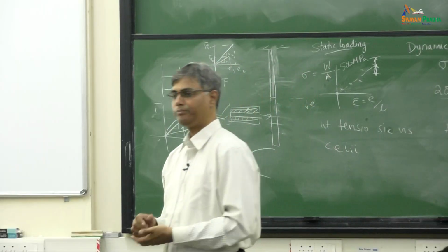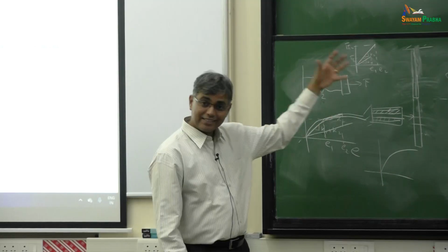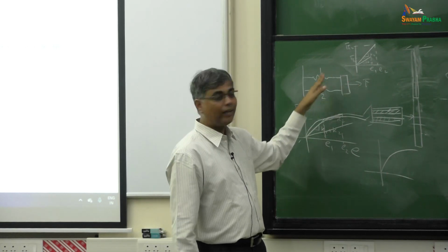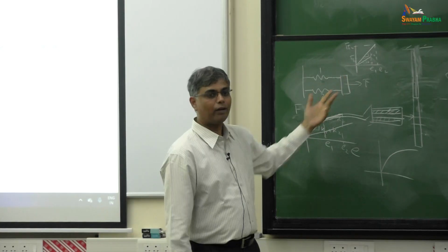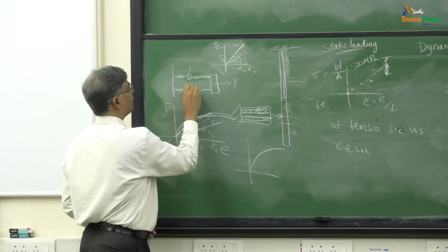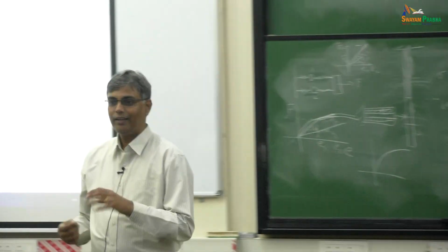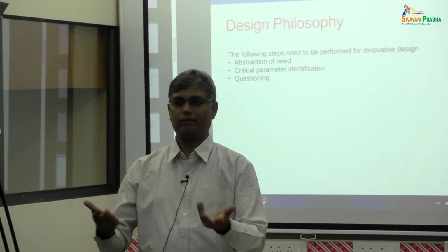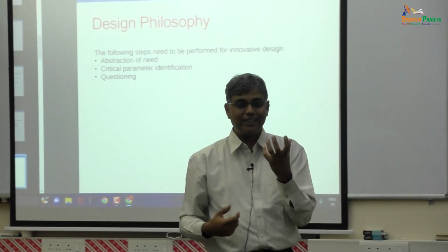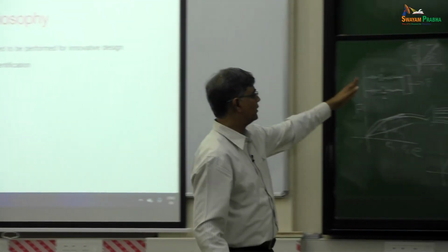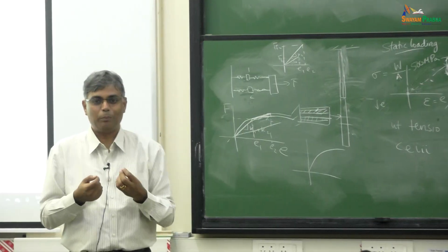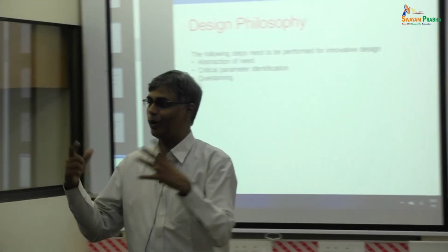But I hope I gave you a flavor mainly about the fact that there are still such fundamental questions that we're literally going back to 11th standard springs and masses. By the way, okay, I've done this with static springs, but of course, I also immediately think, why not put a small mass here? And in fact, put more springs, put them in series, parallel, all of that, and put springs and masses, and then you'll get your spring mass systems that you also studied. So with that, you can get a richer description of the material behavior. So what will happen is, because these things are vibrating when I'm pulling it, that vibration itself will cause some local damage to accumulate, and that will give a better description of the overall fatigue life and so on.